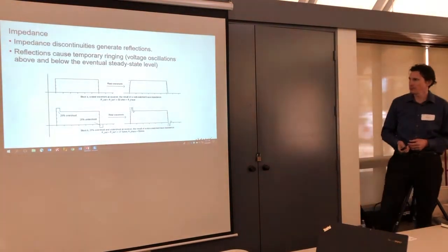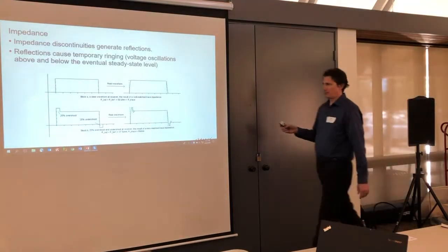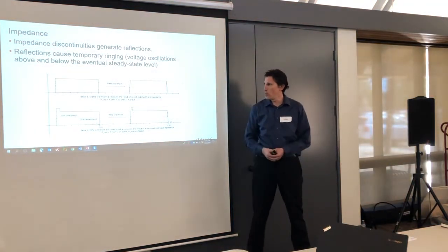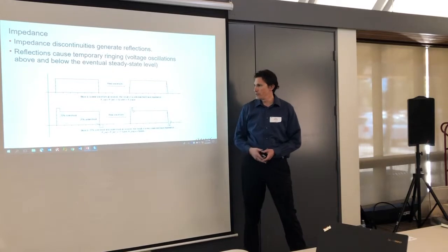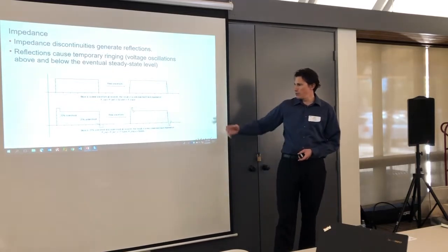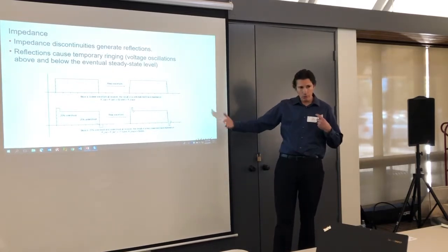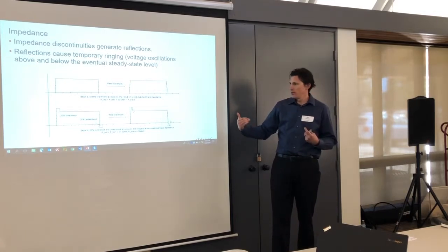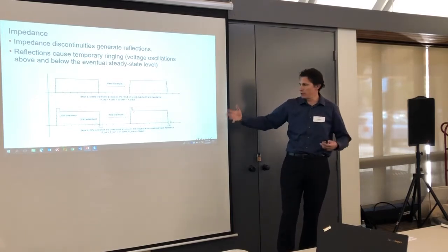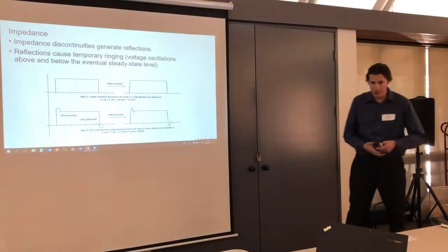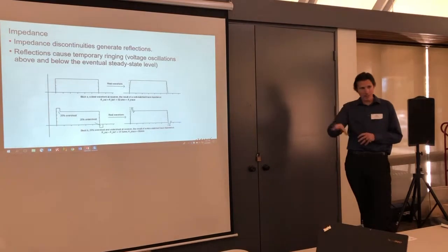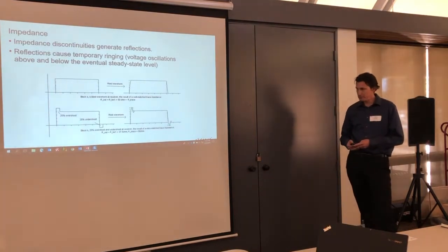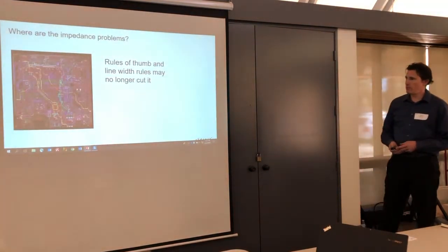sending device sent out. Looking at the same ideal perfect waveform, when everything is matched impedance, there's not a lot of distortion on the receiving waveform. But if you have an impedance mismatch or an impedance discontinuity, you're going to have overshoot and undershoot measured at the receiving device. So it's kind of the same thing as having a back drill issue. It's just another cause of extra glitches in what you would like to be a perfect 1 and 0.